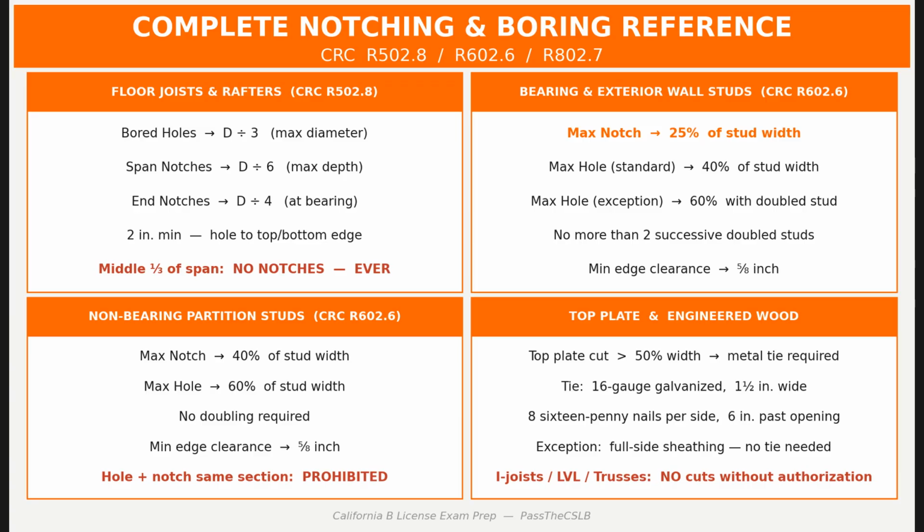Non-bearing partition studs, 40% maximum notch depth. 60% maximum hole diameter with no doubling required. 5/8 inch edge clearance still applies. No holes and notches at the same cross-section.